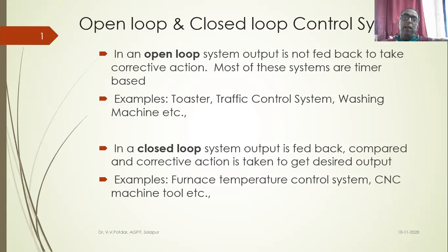And then the feedback signal corresponding to 900 degrees Celsius, I have got a 9 volt feedback signal. Now the comparator compares 10 volt with 9 volt. Well, the error is 1 volt. Accordingly, the corrective action is taken by the controller, and accordingly the heater will be put on for some more time. And once again the sensor senses, and it will show 950, 980, maybe 1000. And when this 1000 signal is fed back and compared with the 1000 set value, the error signal becomes 0. Till that time, this closed loop cycle keeps on working.